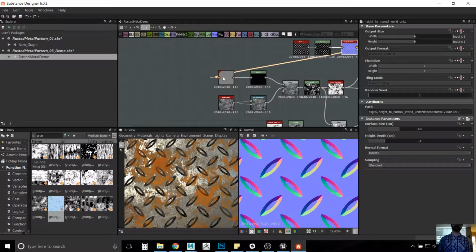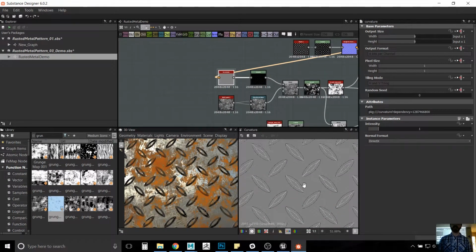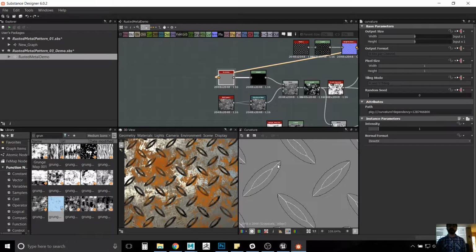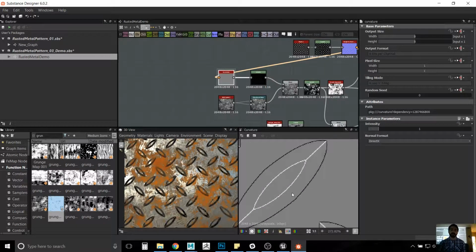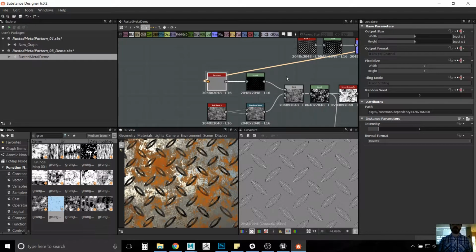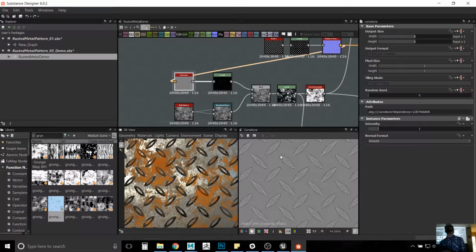Give you an idea, this is what a curvature map looks like. It is a grayscale map that is defined, that's kind of your smooth surface, but any edges will be highlighted in white. So that's what these are. These very extreme edges in direction, or extreme changes in direction, are highlighted in white. So using that, I had the intention of using this to find the edges so that I can have rust along my edges, as if it were occurring naturally. Otherwise, my rust would just be haphazardly all over the thing. I want this to look realistic, and I want it to act realistically.